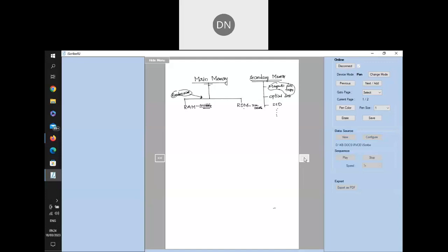Whereas the main memory, which is built using semiconductor integrated technology, the time it takes for reading any word, the time it takes to write any word, is always fixed. So it's also called random access memory. You can randomly access any of the locations with the same time. So this property is present both in case of a RAM and the ROM, because in both places we use semiconductor integrated technology. The only difference between ROM and RAM is one is volatile, the other is non-volatile.